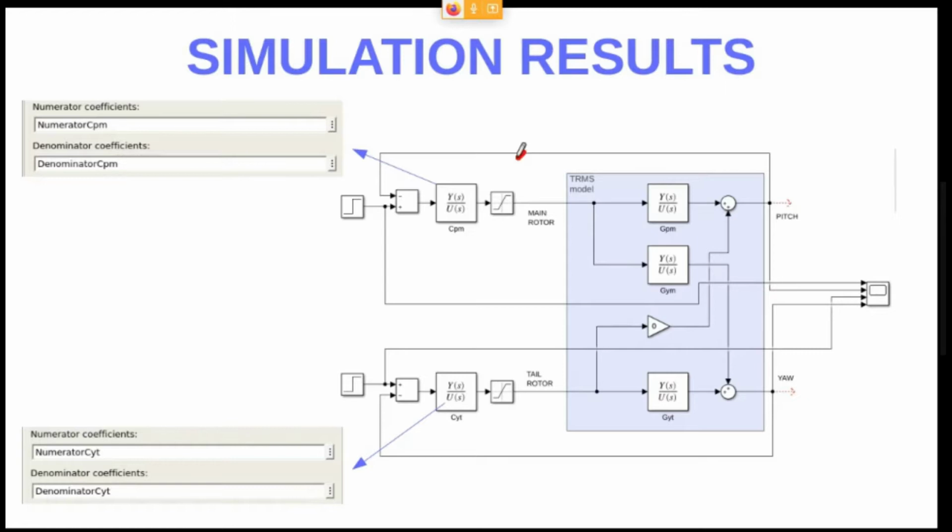A very important thing here, we have a limiter block between 0 voltage and 10 volts, because this will be the maximum value for the real system, right? And this will be the minimum value. So no negative values for this manipulated variable. And the same goes for this, right? Here we have also a limiter.